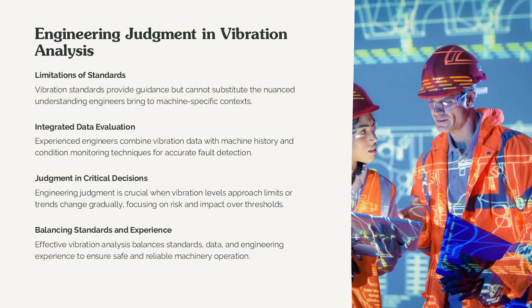Vibration standards and charts provide valuable guidance, but they cannot replace engineering judgment. Every machine operates within a unique mechanical and operational context that influences vibration behavior. Experienced engineers evaluate vibration data in combination with machine history, maintenance records, operating conditions, and other condition monitoring techniques such as thermography or oil analysis. This integrated approach reduces false alarms and improves fault detection accuracy.